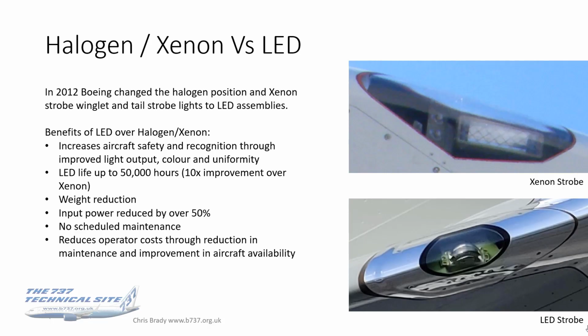These are, as quoted from the Boeing blurb, increases aircraft safety and recognition through improved light color output and uniformity. In other words, it's brighter. LED life up to 50,000 hours, which is a 10 times improvement over xenon. So that is significant, and that is rocking on toward the lifetime of the aircraft.